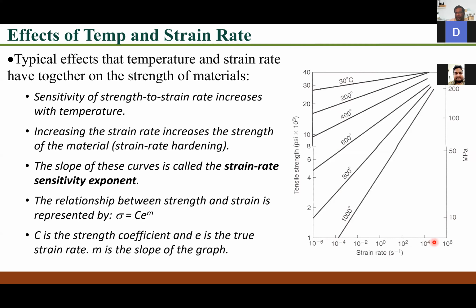But if you look at a very high strain rate, you can see here that again the same phenomenon is there. However, at a high strain rate, the strength is higher than what you get at a low strain rate. Again, because of the dynamic application of the load, the material strength also increases. So that also we have to take into account.